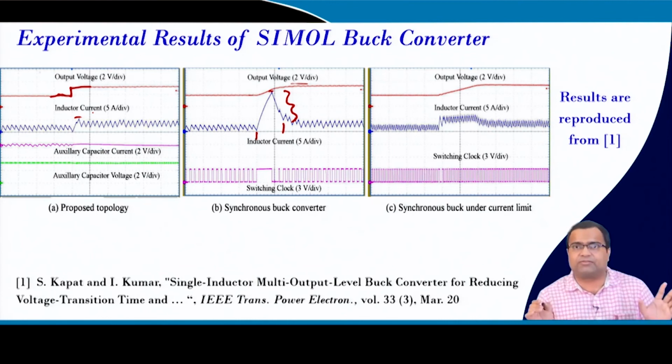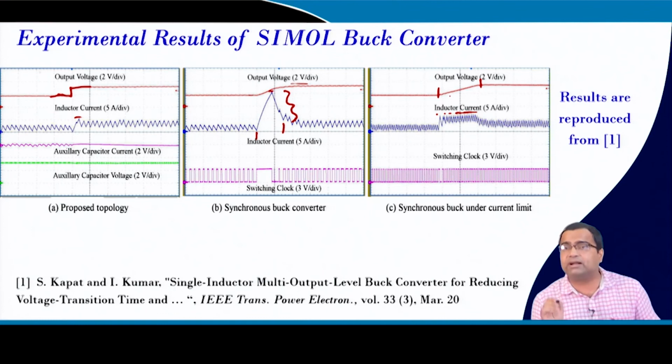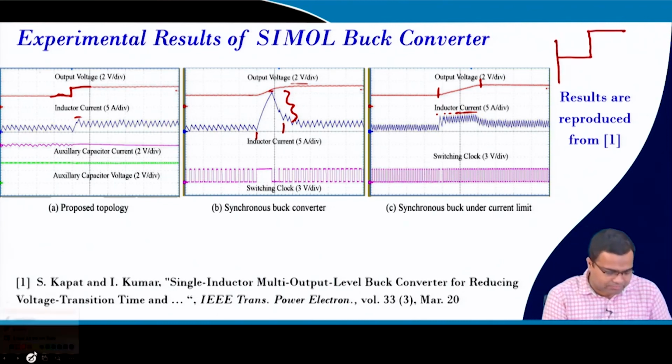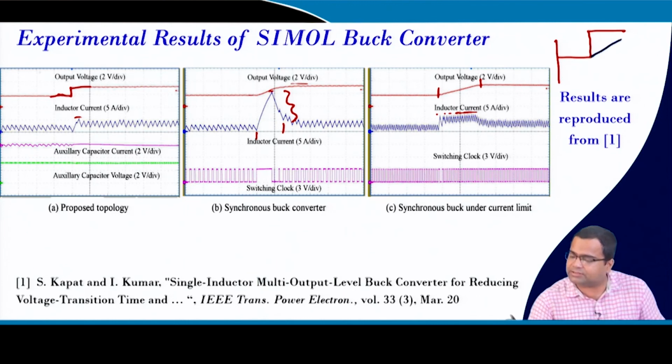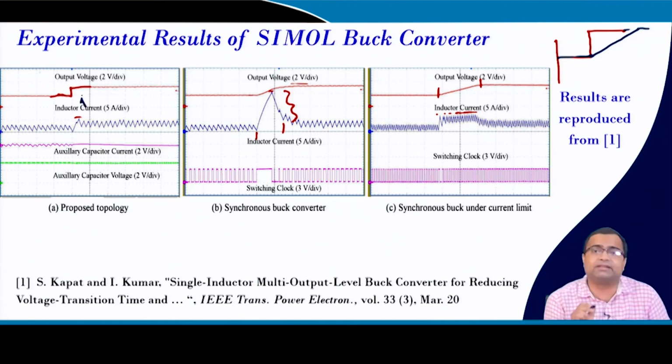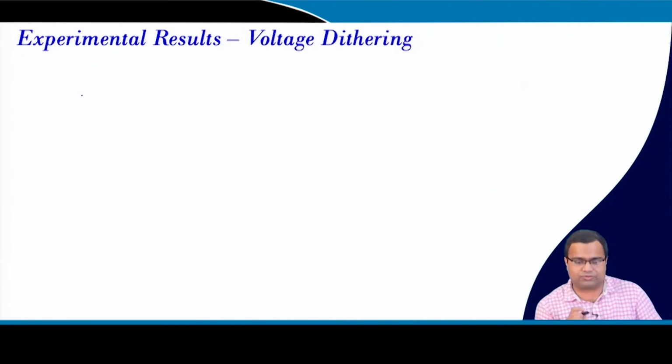Now, in a conventional converter, if we want to put in a current limit, because there is a limit on the inductor current, since we are using peak current mode control, then naturally the recovery time increases, and that is not acceptable. And if the recovery time increases, then your processor power supply, this is the ideal processor power supply requirement, but it actually changes very slowly from this part to this part. So, your uncertainty will increase further because it takes longer to reach from one voltage to another, but here you can make it almost immediately without any current overshoot.